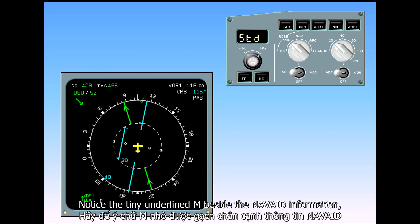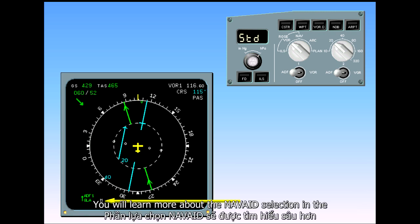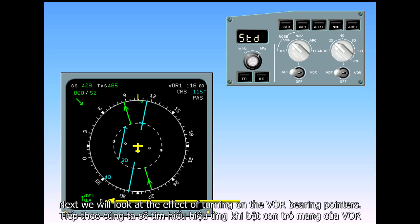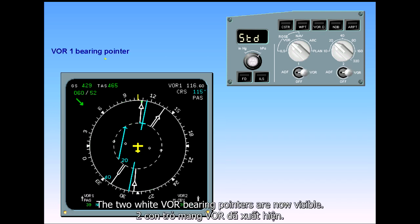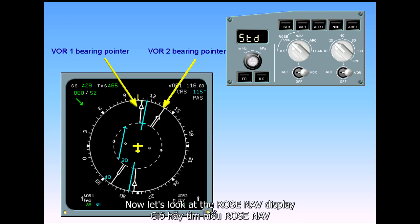Notice the tiny underlined M beside the nav aid information, which indicates that the ADF has been manually tuned by the pilots. You will learn more about the nav aid selection in the navigation chapter. Next, we will look at the effect of turning on the VOR bearing pointers. The two white VOR bearing pointers are now visible. You have seen the two raw data displays. Now let's look at the rose nav display.